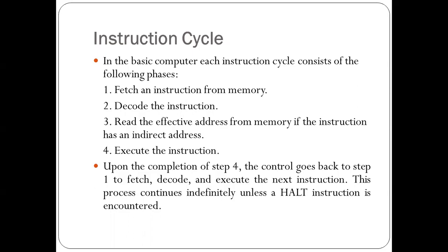As and when the PC is loaded with the first instruction address, the computer has to fetch the instruction from memory, reading the instruction from memory and loading it into the instruction register. After that, the decoding circuitry will decode the instruction.